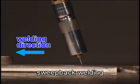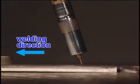Contrary, when the torch is angled opposite to the direction of the travel, it is called the sweep back or drag welding method. Generally speaking, forehand welding method is more common since it is easy to observe the weld joint, bead appearance, and shield gas effectiveness.